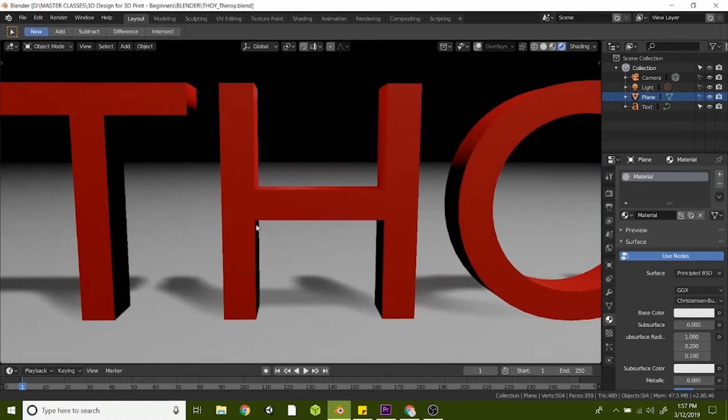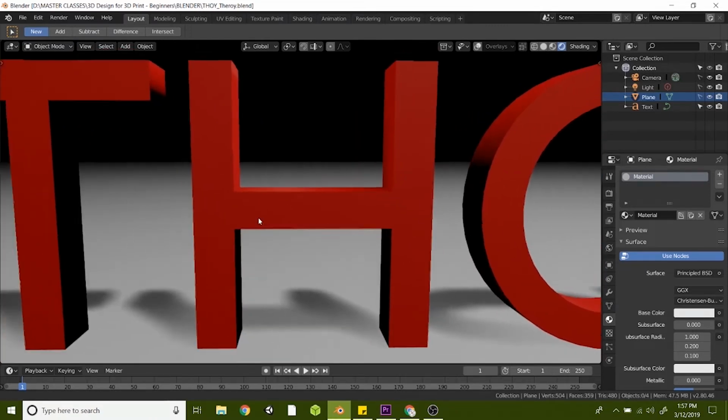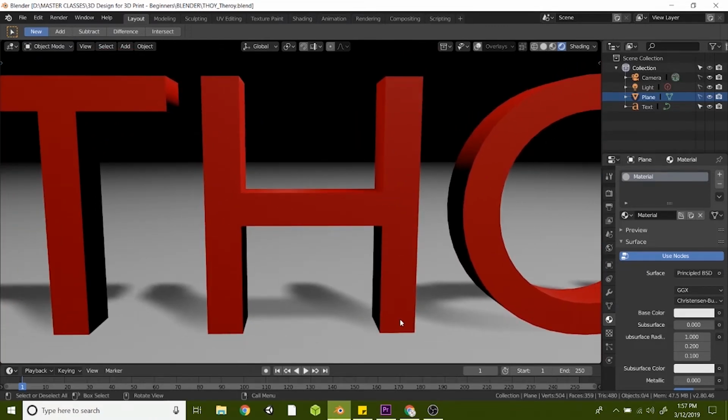Next we have the H, which represents bridging. What I mean by that is when the printer goes to print this H here, it would come up and build the feet, and then when it gets to this point, it would actually create a strand of melted filament that creates a bridge, and then the printer could continue printing this entire shape. So the H is allowed, and you just want to be clever because you could have your own internal bridging inside of your designs that help you to 3D print without the need of support material.